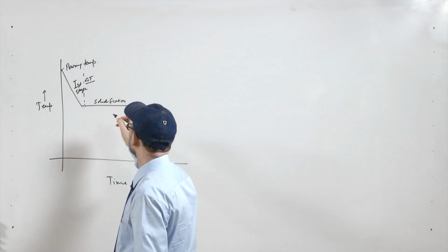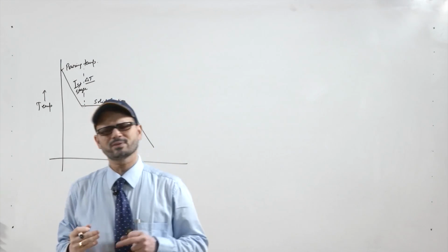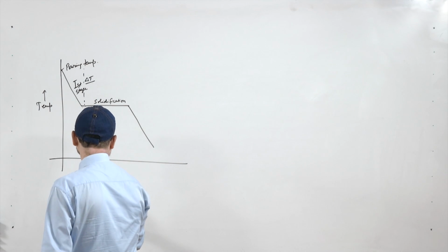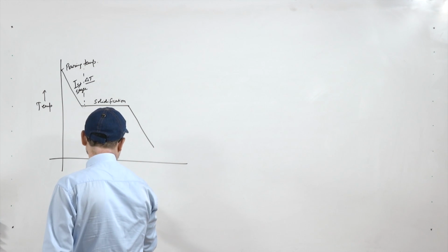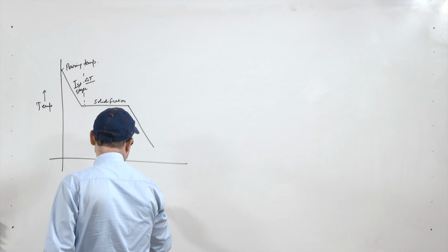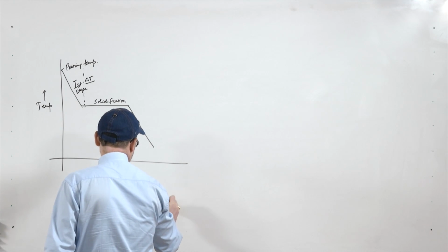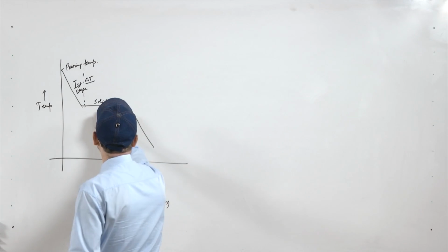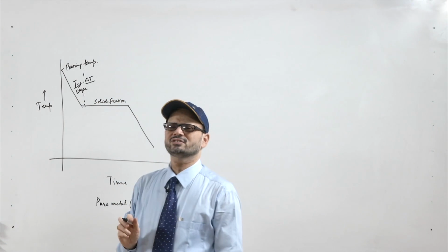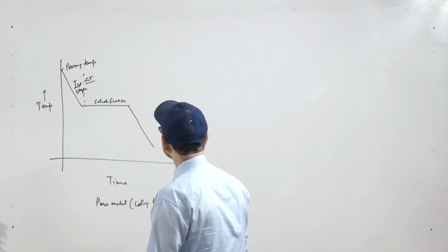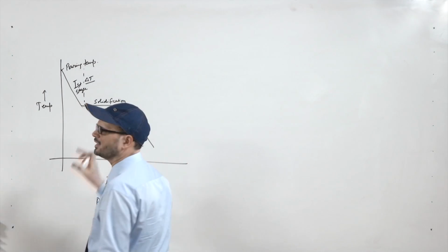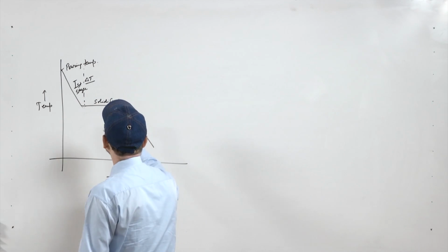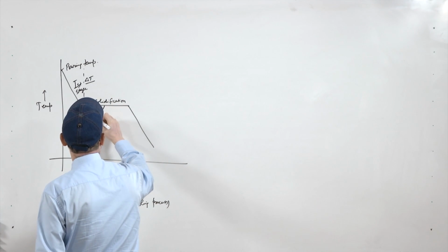The metal tries to release the latent heat during the process of solidification. For pure metals, during this process, although the temperature does not change, it takes time to completely solidify and reach this point. So, during this process also there will be some contraction in the metal, and this contraction is the stage 2 contraction.